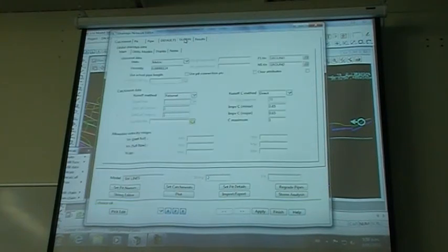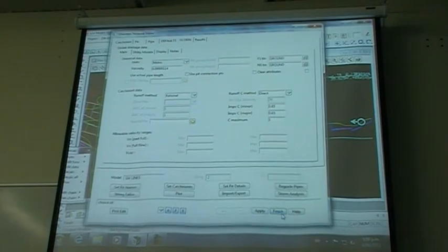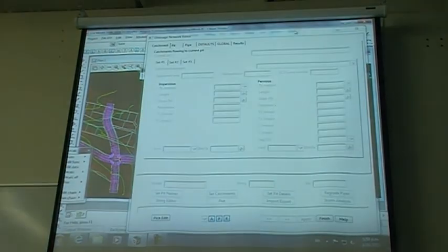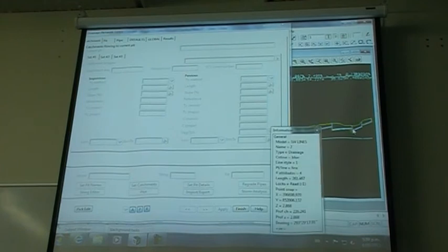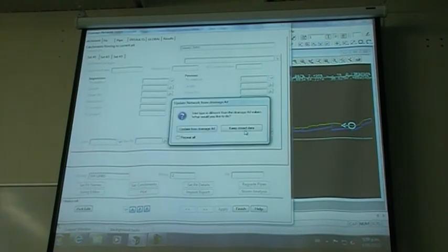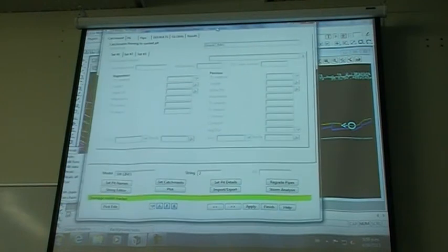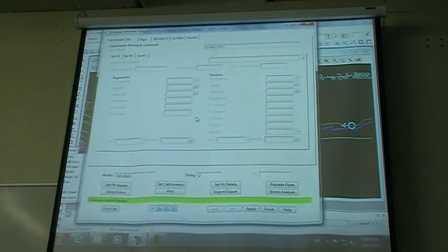How did you click the line, sorry? Okay, so I just go drainage network editor. You can either click down on pick edit or it's already actively looking for it. So I just go to any point on my drainage line, pick and accept. Okay, just like last week when I do the setups, I work up on these top tabs. I start on the right and I work back to the left. And when we start to actually manipulate the line, it's the opposite. We start on the left and work to the right.